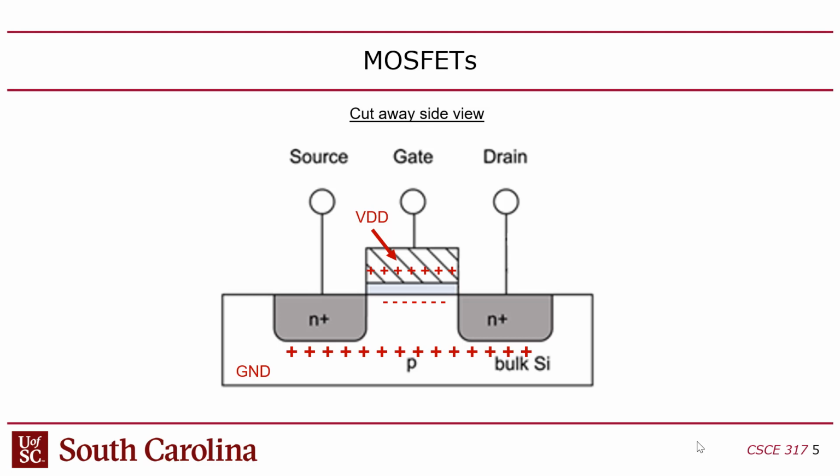Because the logic gates have a capacitor on the gate, the job of this guy is to charge and discharge those capacitors as fast as it can. The faster it does that, the higher your clock speed is, right? Well, the problem is that how do you charge and discharge capacitors fast? You need more current, right? But the problem is you're limited in how much current these guys can send out, because they have the saturation mode. And so that's really what drives the entire semiconductor industry and computer chips and Moore's law. It all depends on how much current you can get through this guy, right? Ultimately, that's a very important thing about what computer engineers are doing when you're trying to make these things faster and more capable. Now another thing you could do also, you could reduce the capacitance here too.